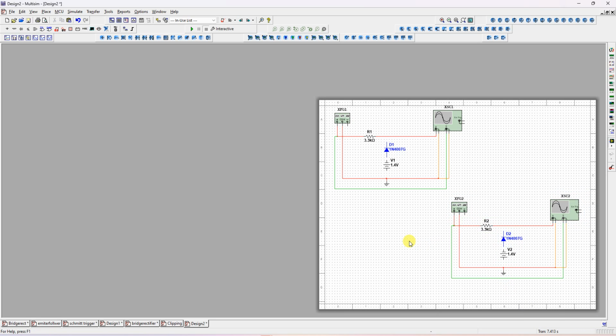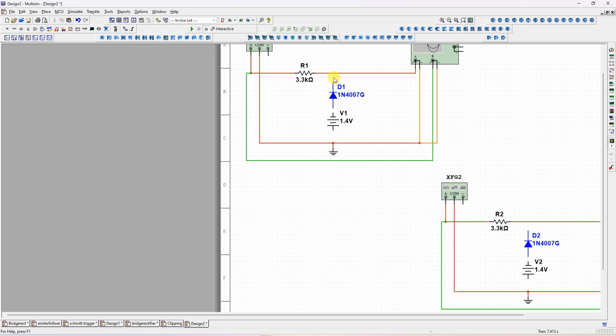So there is no need to once again pick and place the components. The first time, if you want to do it, refer to my positive peak clipper video. This is just to save time. I'm just showing how to reverse the diode. For that, I just deleted this red color line and this red color line, so that if I rotate now, the other connections will not be affected. That's why before rotating, I removed the connected part. Now I rotated two times. So join this, join this.